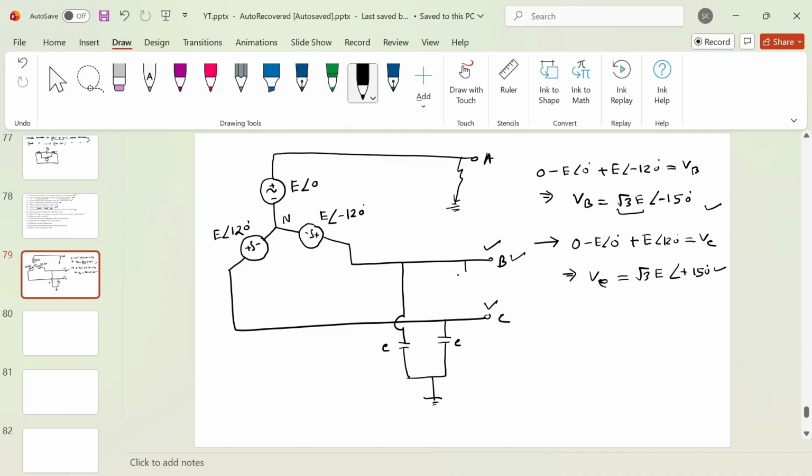You'll be having the insulators connected in the lines, like suspension type insulators and all. So this insulator breakdown voltage is decided by the peak voltage of the phase voltage. But here the voltage has increased. Now this voltage may damage the insulators. So this is the disadvantage for us. Now we will see what is happening here.